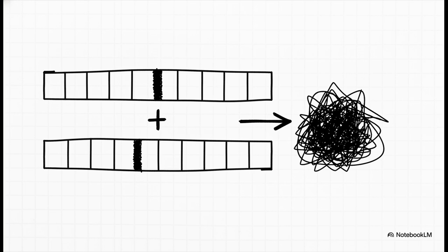What happens when we need to add things together? A classic example of this is computing an FIR filter, where you're accumulating multiple multiplications. The absolute golden rule here is this: you cannot add numbers with non-aligned binary points. I mean it. If one number has a scale factor of 2 to the 8th and another has a scale factor of 2 to the 9th, adding their raw integer values together will literally just yield complete gibberish.